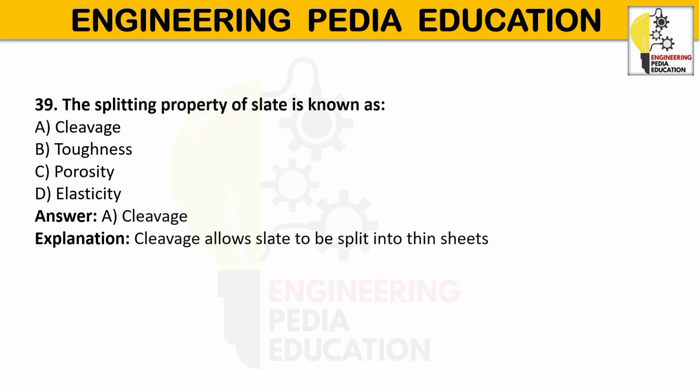Mica also shows perfect cleavage. Engineering significance: useful for dressing and shaping stone. Excess cleavage in building stone may reduce strength in certain directions.